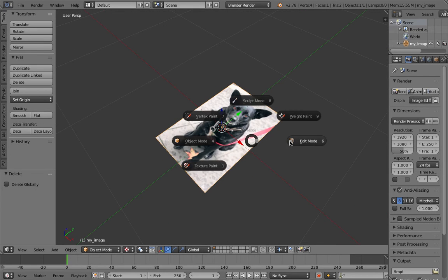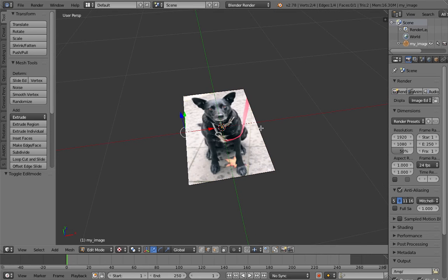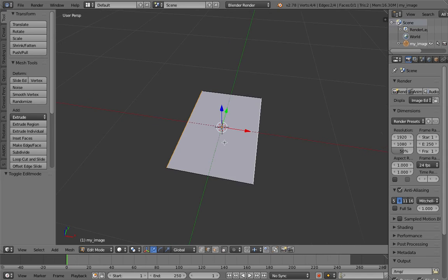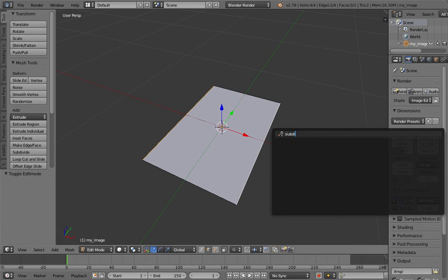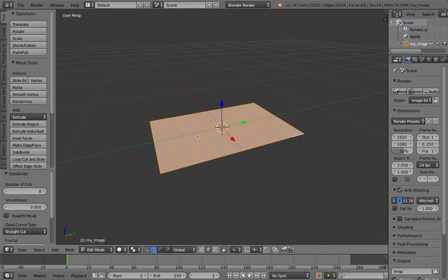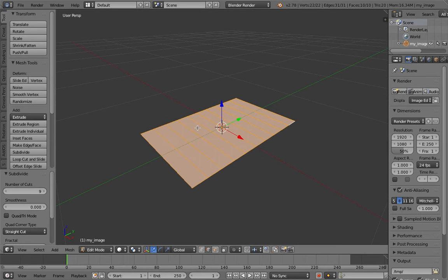In Blender, if you go to edit mode, you can do some cool splitting, like with the edge, for example. I'm selecting this edge and that edge on the side, and then what I'll do is just hit spacebar and then subdivide. Mesh subdivide, and then turn it into how many? 8 subdivision? 1, 2, 3, 4, 5, 6, 7, 8, 9. Oh, 8 give you 9. 9 give you 10. 1, 2, 3, 4, 5, 6, 7, 8, 9, 10. Okay, cool. That's the plan.